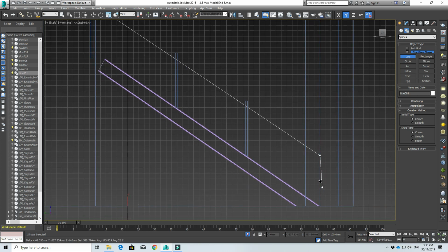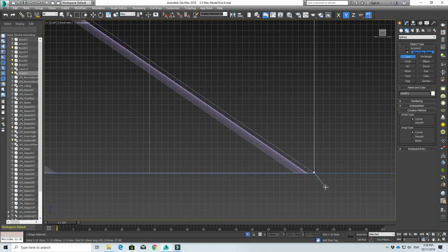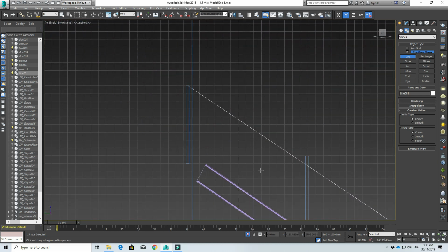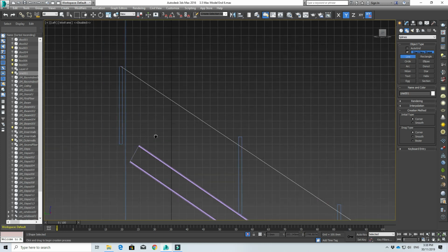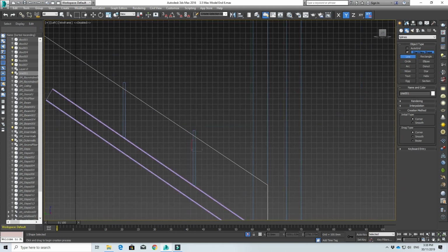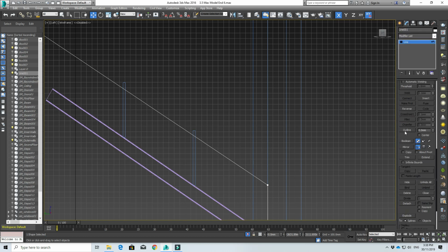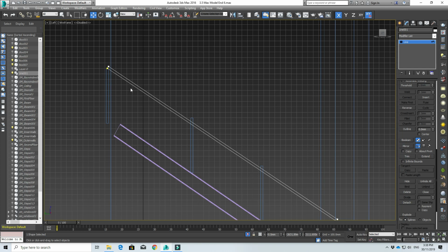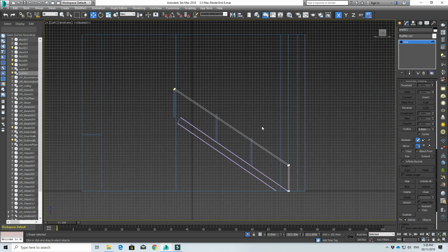And then after that, okay, so once we have the line, again, you can use the Boolean method I teach you to remove all this later, but for now, let's just take the line, go to the spline to highlight the spline, and then go to the outline tab and type 40. Okay, so this will create an outline. Let's go to the top view. Okay, so this is still in one line. Okay, and then we will extrude.